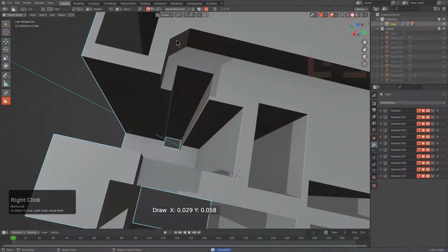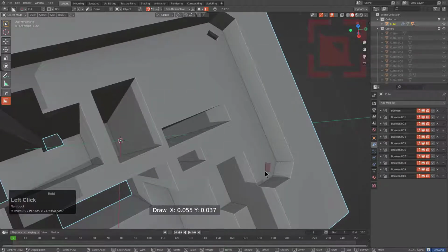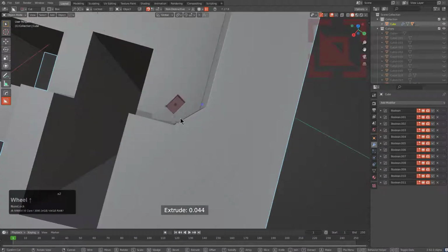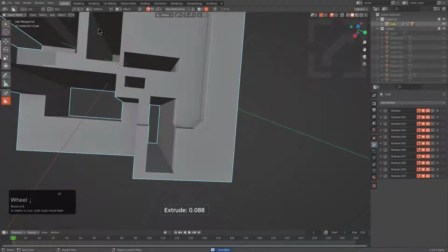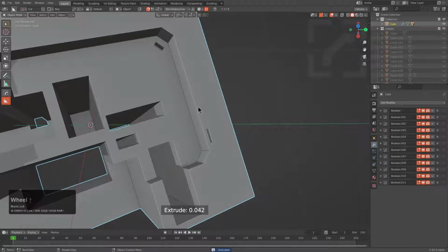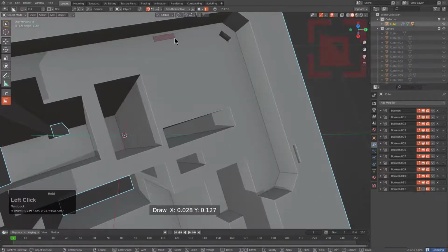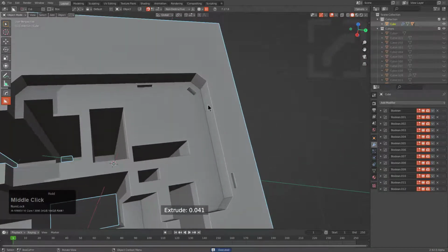And so let's try the same thing here. Still isn't going to allow us to work. So we see that it's not the most reliable way to work, just changing your orientation on the fly. In fact, this cut almost looks like it was at the right orientation, but it isn't. So we can go back to our orientation panel and change it from nearest edge to longest edge and hope that that improves things. But you know, the longest edge nearest to the cuts that we're starting is more than likely these long boundary edges that actually trim our bevels. So whenever it comes to dealing with orientation, there's a lot of different ways that you can approach it.